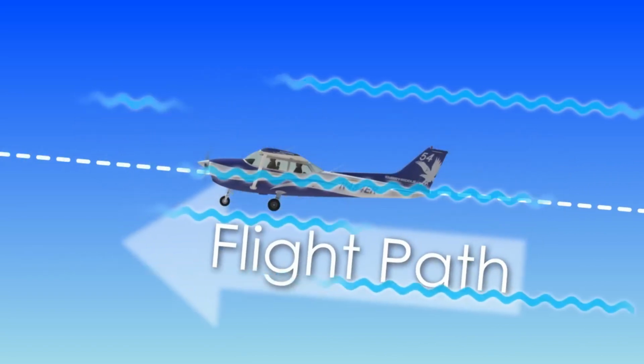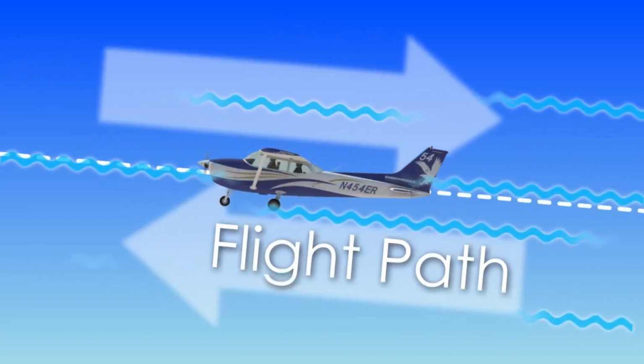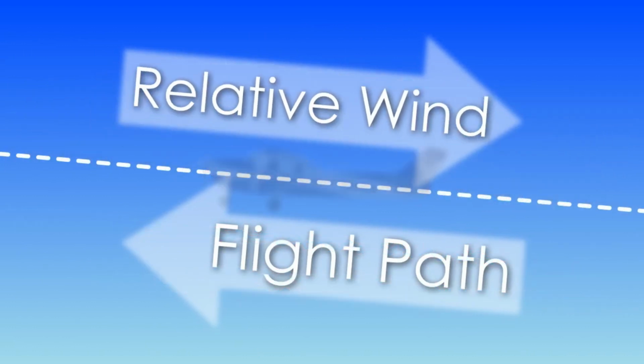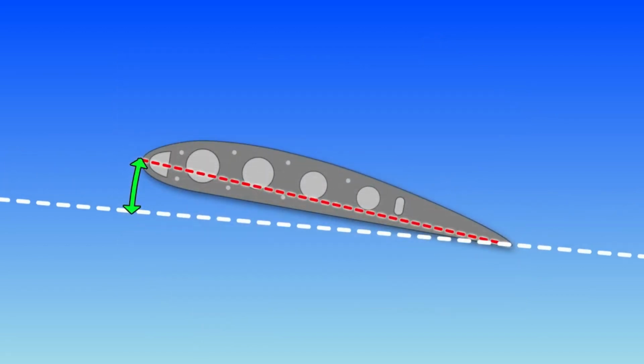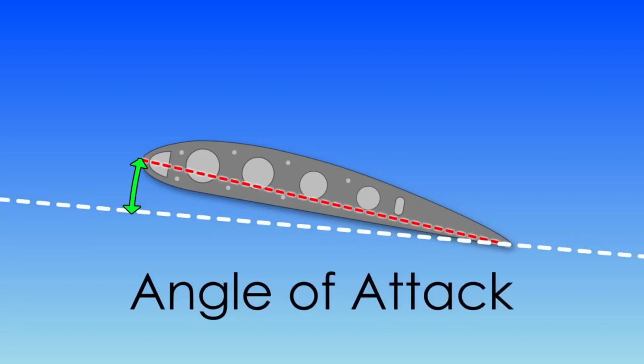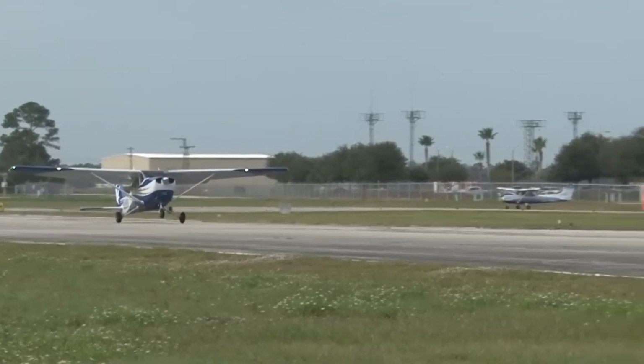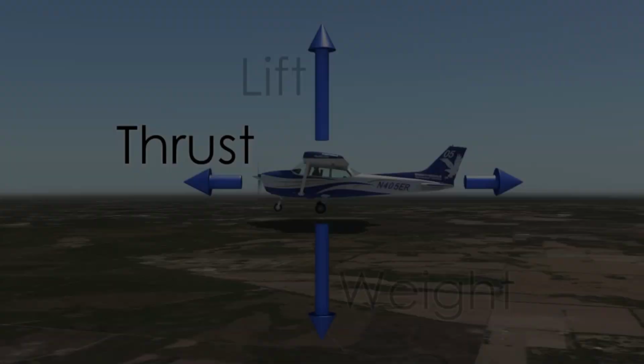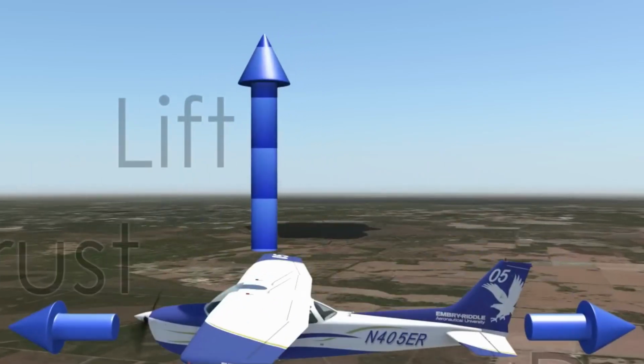This pressure requires energy that is taken from aircraft performance, speed. Therefore, when the CG is closer to the aft portion of the aircraft, the elevator downward forces are less. This results in less energy used for downward forces, in turn resulting in more energy applied to aircraft performance. Thrust is controlled by using the throttle to establish or maintain desired airspeeds. The most precise method of controlling flight path is to use pitch control while simultaneously using power, thrust, to control airspeed. In order to maintain a constant lift, a change in pitch requires a change in power, and vice versa.